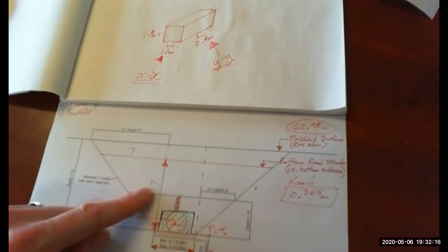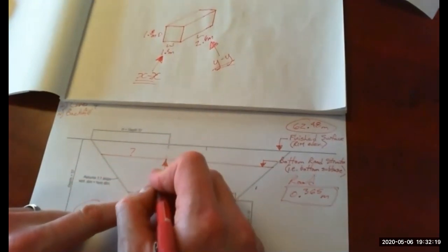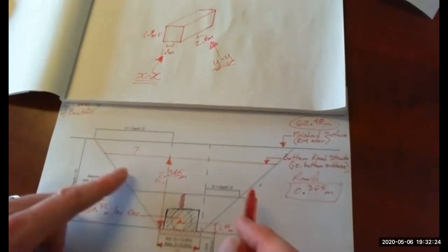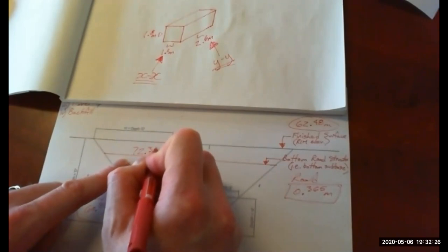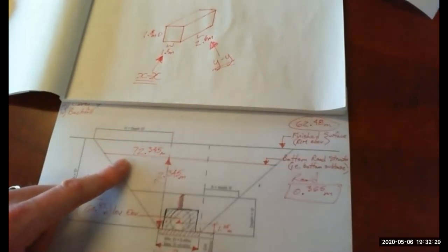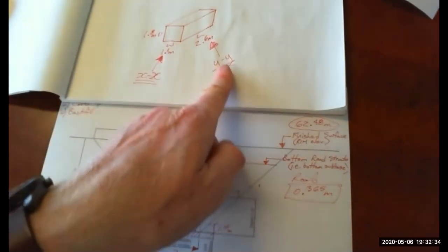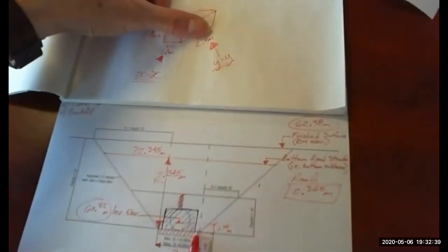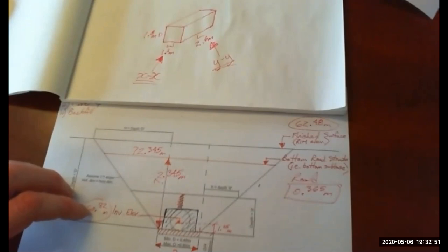So that depth doesn't change, so it's the same number that we just calculated. I'm simply copying it off of the previous section that we did. Same thing with this number. So the only number that's going to change is the width down here. Because we're looking at the Y direction, the length of the concrete here is 2.6. And I said we were going to add 0.15 to each end. So 2.6 plus 0.15 plus 0.15 is 2.9.